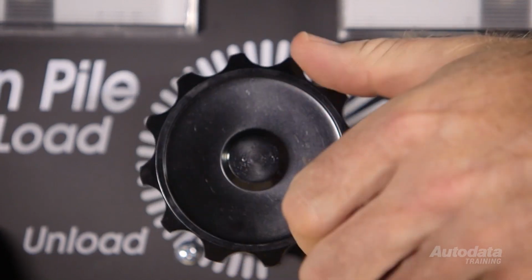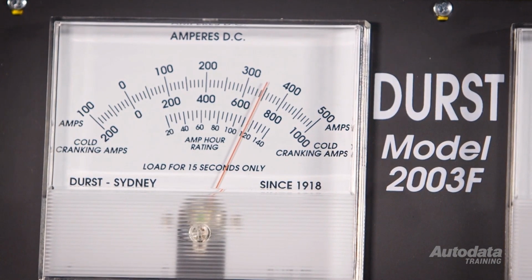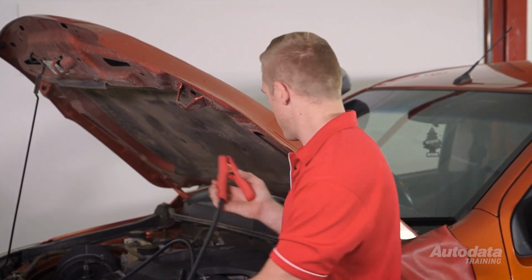Prior to diagnosing a communication fault, perform a battery load test. A weak voltage supply may be the cause of the communication codes. Don't forget to connect a battery maintainer to ensure stable voltage readings when performing voltage checks.